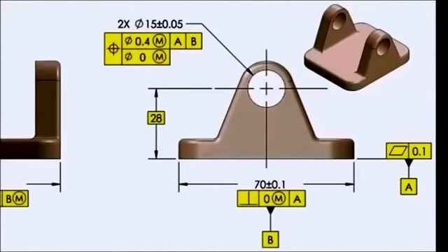Since there is no datum feature reference in the lower segment, the coaxiality of these holes may be checked with a simple pin. The next 2 tips in this series will illustrate how a 3 or even 4 segment composite tolerance may be inspected using hard gauging.